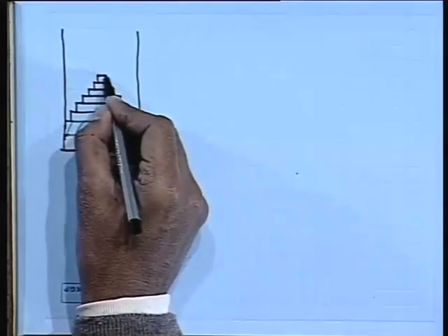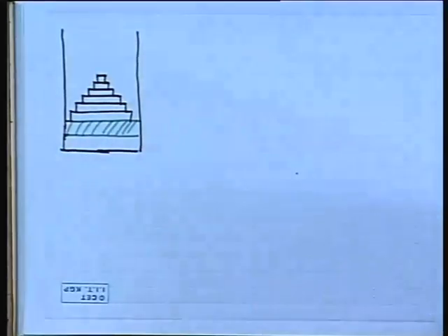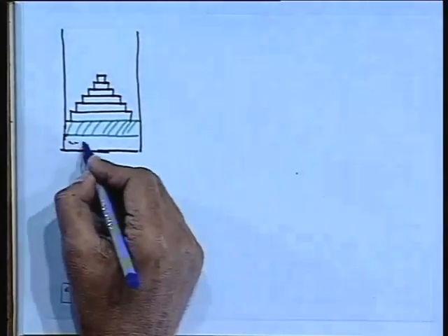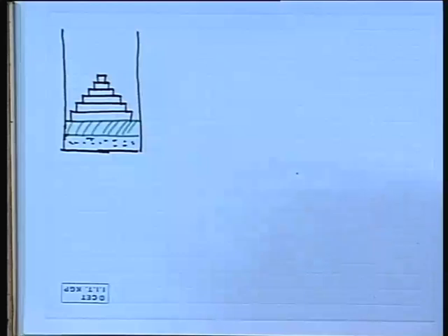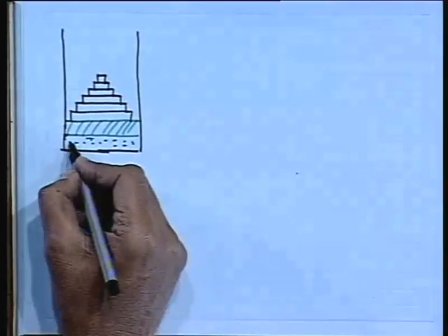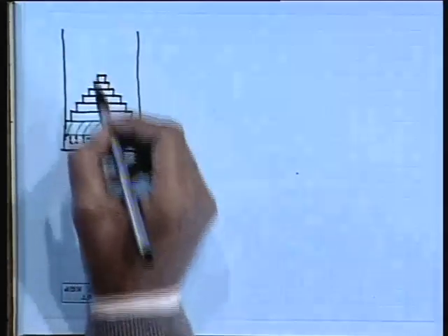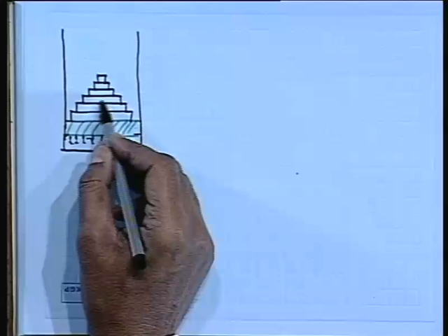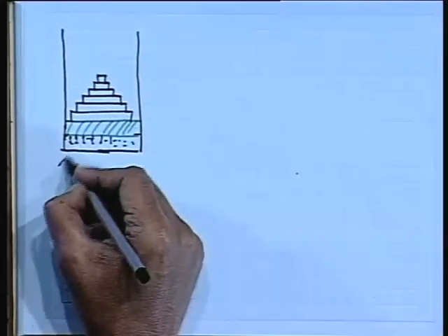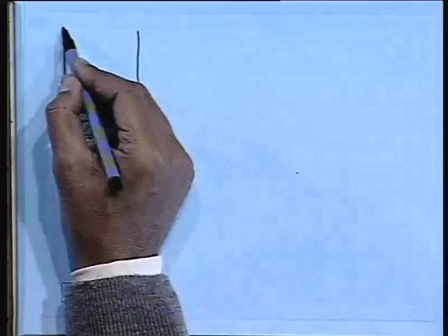Number of weights. And let us consider that there is some gas within the cylinder, and consider this gas as a system. Now this gas exerts some pressure, and at the initial state let us consider the weight of the piston along with the external weights balance this pressure P. Let this pressure be P1 and initial volume be V1. The system is at state 1.